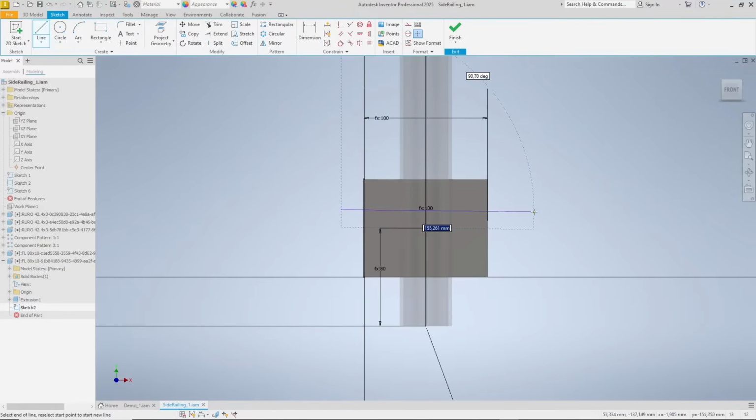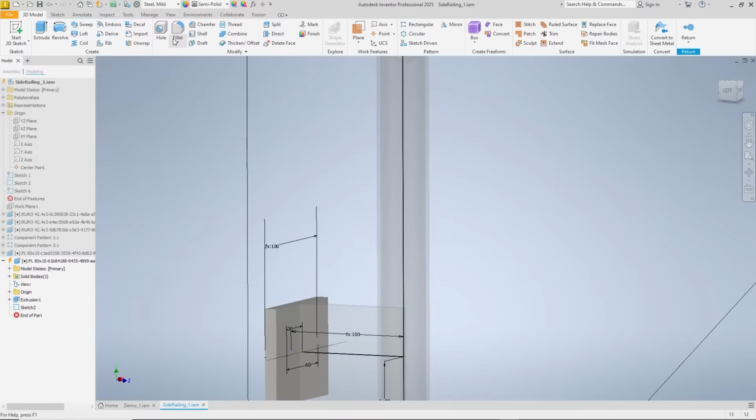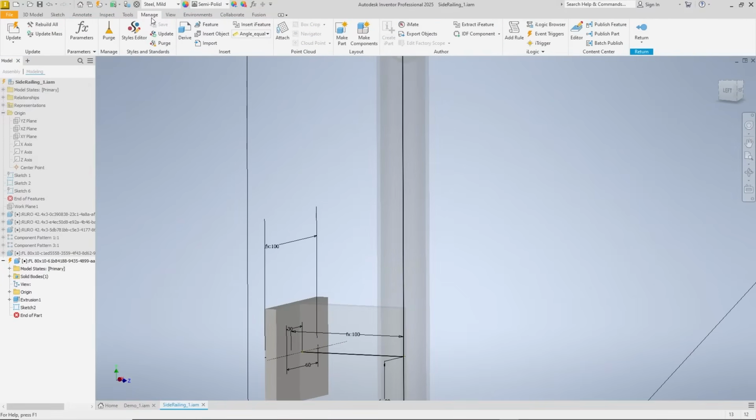First, we insert an auxiliary line. Center it vertically on the profile and add 2 sketch points. We dimension the distance between the left point and the center at 30 mm and the distance between the points at 60 mm to achieve a symmetrical arrangement and finish the sketch. These 2 points will allow us to place the bolting precisely later.